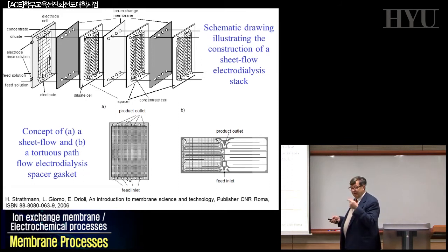If you have this membrane available, we will see that the efficiency of the cell that you are going to create is very much related to the engineering of this system, how you build this. Because this is a system in which you have a lot of phenomena. You have diffusion between anodic and cathodic compartment across your membranes. After that you have migration due to the electrical field. After you arrive at the electrode compartment, you have a transformation of ions, oxidation reduction, with production of electrons.